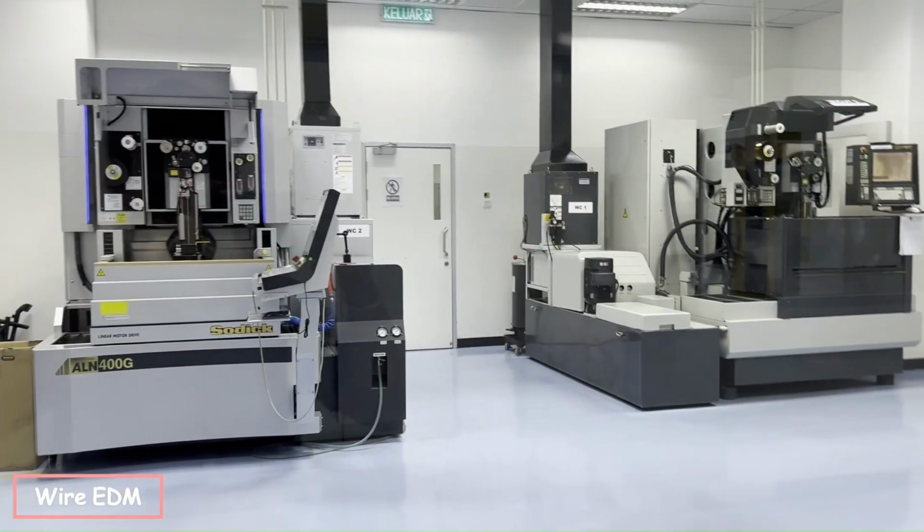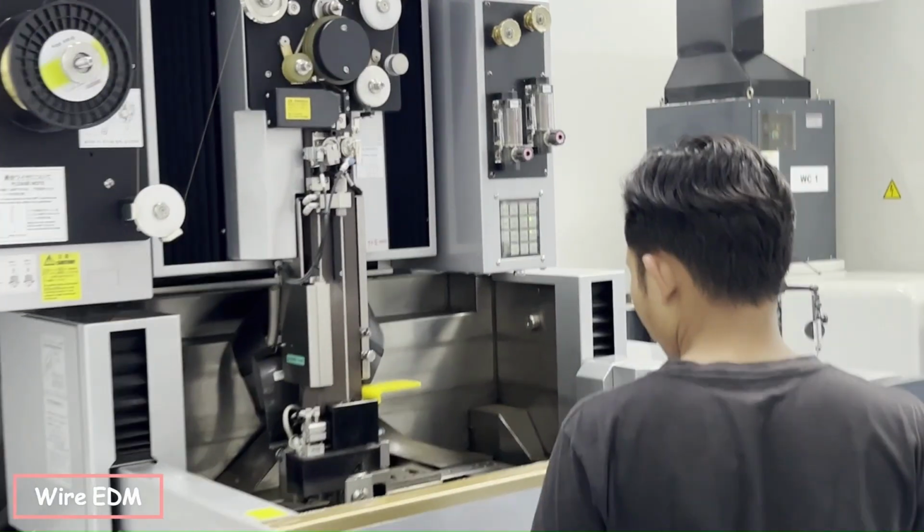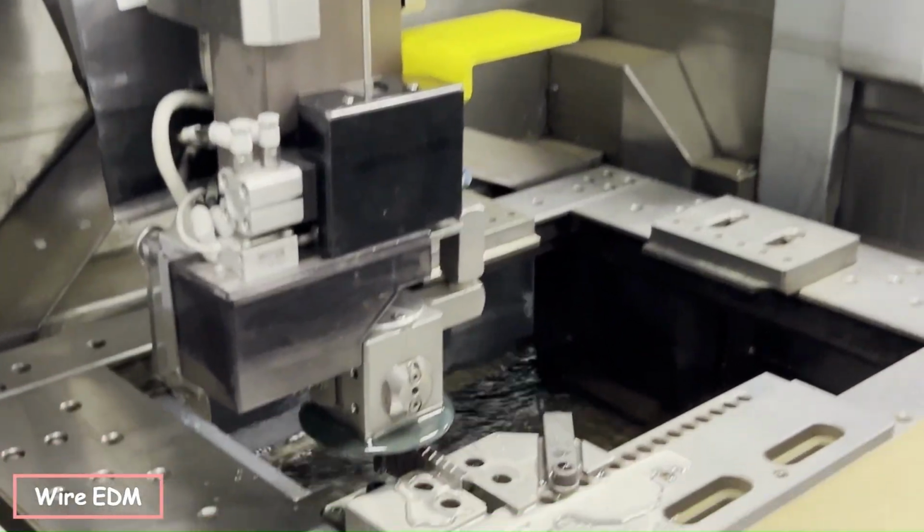The wire EDM machine is capable of machining hardened or soft material that is electrically conductive, and able to achieve a tolerance within 0.005 millimeters.